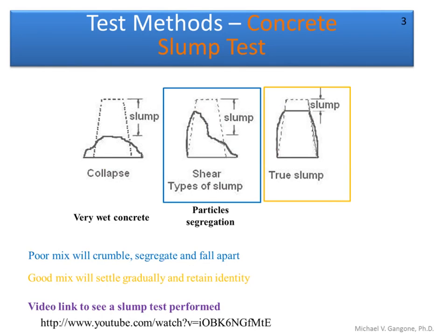Now, if you're using water-reducing agents or some type of superplasticizer to create that high slump, then that might be okay. But if you don't use those and you see a high slump, you might be a little concerned that the strength may not be great. But then again, maybe it will be. It's not a definite thing, but something to think about.